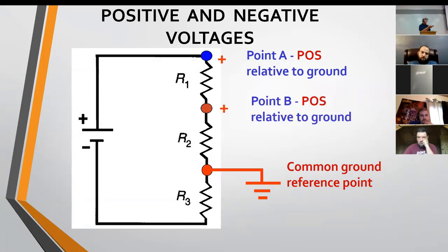Here we're looking at a voltage divider, looking at different reference points. And this is the same thing as with your lab where you're changing the meter leads, because remember that voltage is the difference between 2 points. One point serves as a reference and you're comparing the other point to it. So typically your black lead is your reference point and your red lead is comparing that point, the difference in potential, to the black lead.